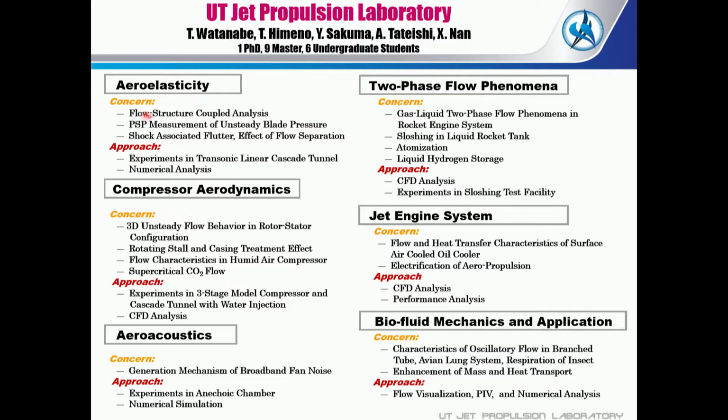Today I talk about aeroelasticity. In aeroelasticity, we are interested in the flow-structure coupled analysis. It's a numerical analysis. And the second one is the PSP measurement, pressure sensitive paint measurement of unsteady blade pressure. And the main concern is the shock associated flutter.